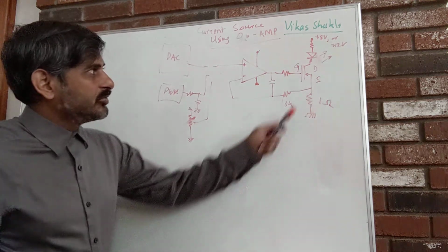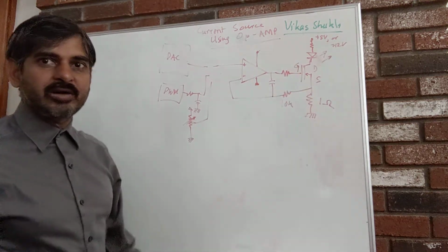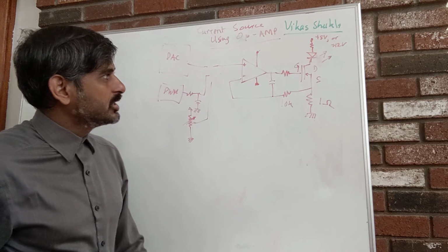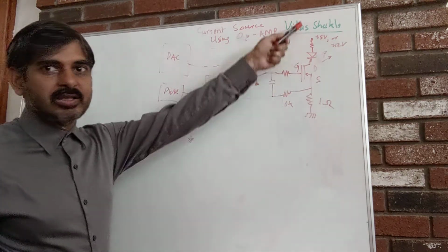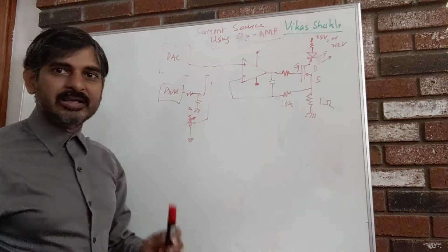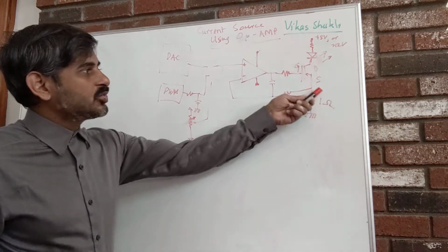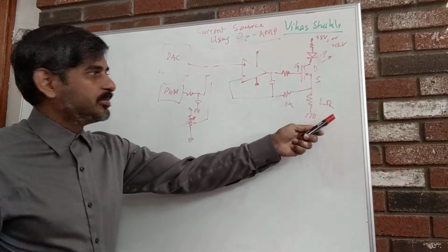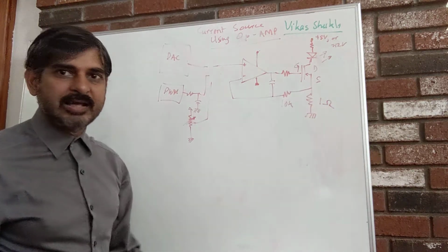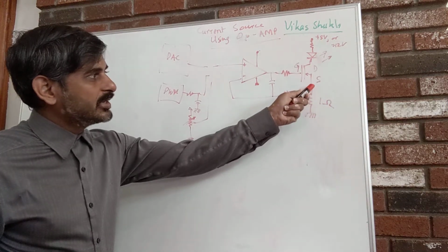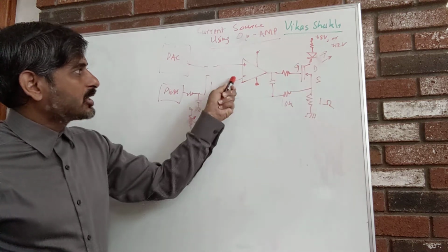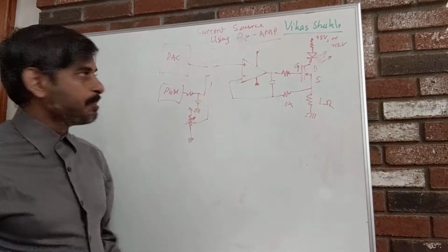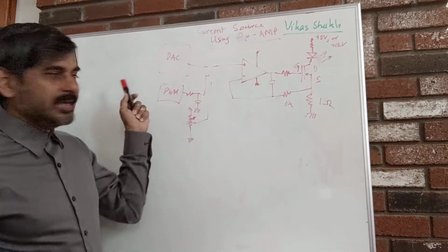So essentially we have a FET here, although a transistor could be used, and let's say if this is high, then the current flows through it. The key here is a very small resistor, typically 1 ohm or something like that, which is used to collect the voltage here, and this voltage is fed back to one end of the op amp. The other end of the op amp